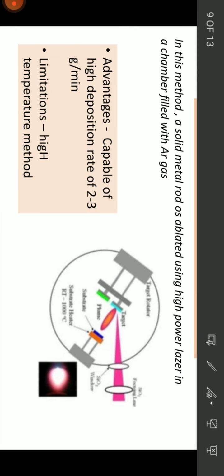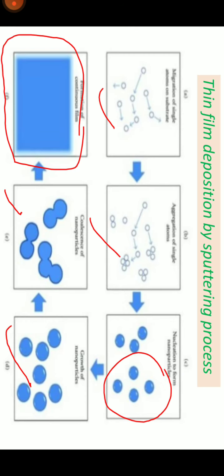Then there are some of the advantages of this sputtering method, that is this technique doesn't require high thermal processing, and no heating is required in this process. Then it works at very low vacuum as compared to the evaporation process, and it's also having some limitations, that are the controlling of deposition parameters is very much difficult, and similarly it's also a high costing process.